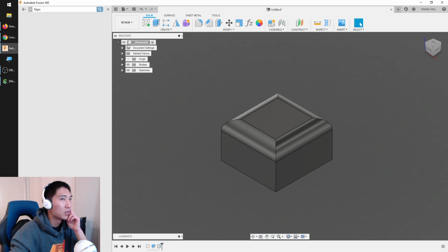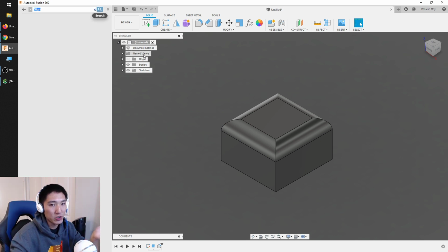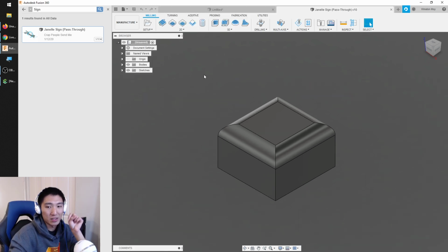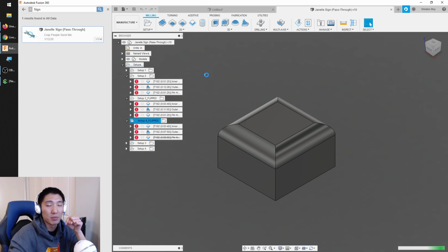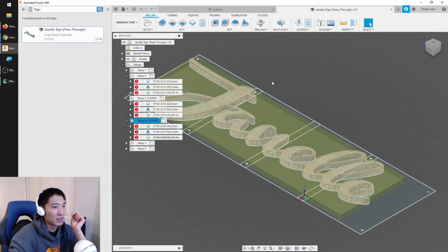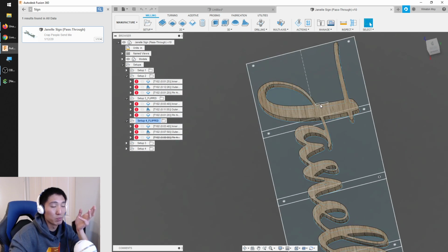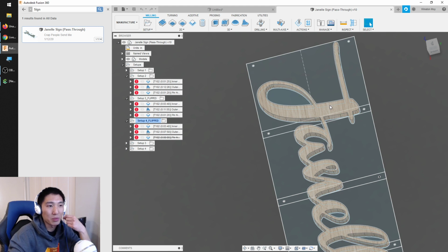Normally in something like Vectric, there's a tiling function. I was using Fusion, so I had to get a little creative. When you're doing multiple setups, you always want to have something you can index off of, so I like to drill holes in known places on my stock, and then if I drill 2 additional holes in the wasteboard, I can always line those things up with an indexing pin.